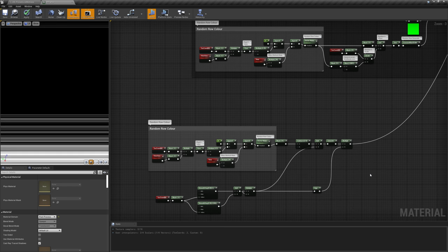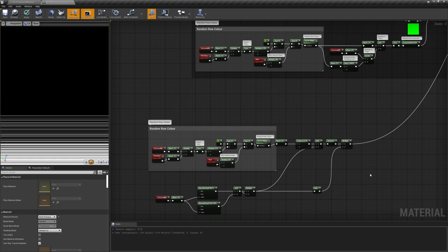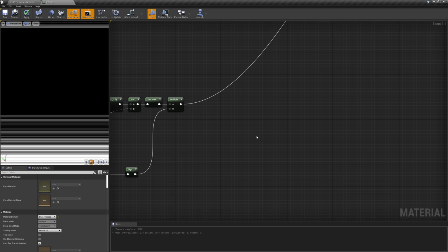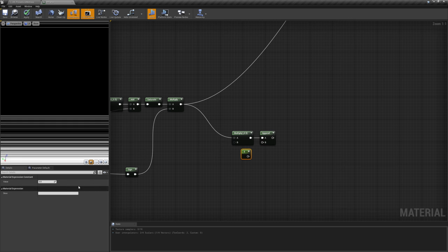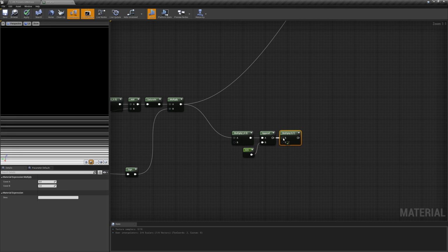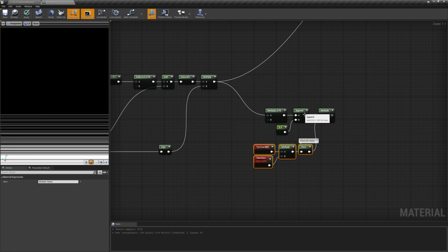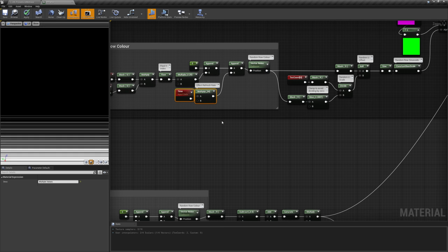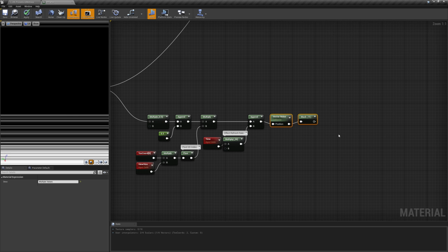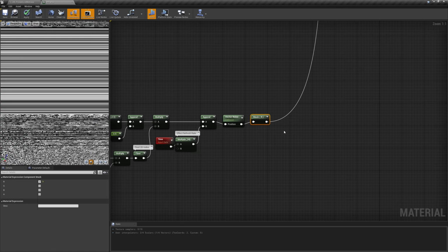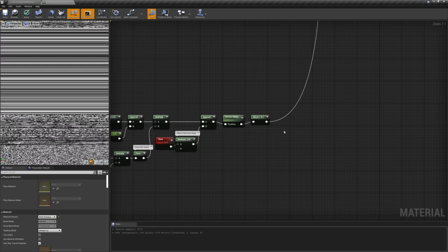This data will serve us to create the noise we're looking for, by acting as a variation for the input of a new vector noise node. Let's scale it by some factor and the pixel to the index, append to it our refresh rate, and plug everything in a new vector noise node. We now have a denser noise where the degradation intensity line is wider.